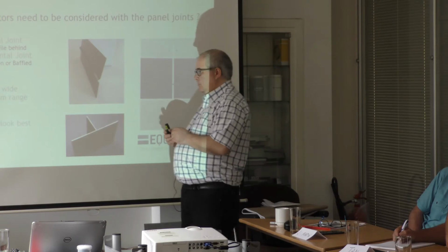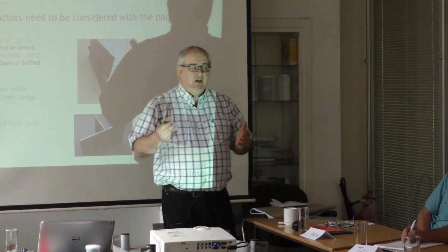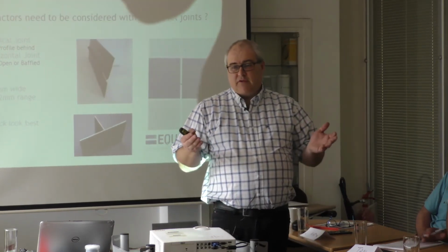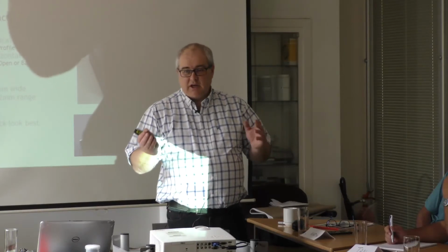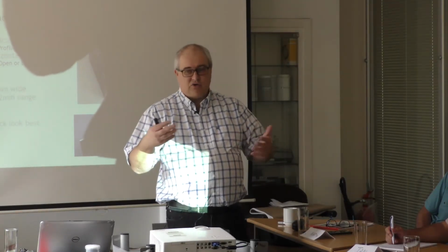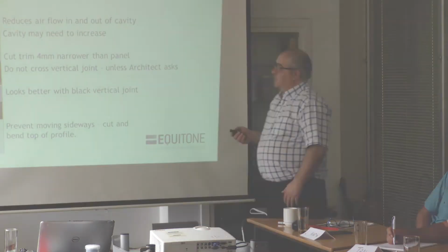Okay? It also makes setting out a lot easier. A lot of the time I've seen on architect's drawings to give you the size of the panel. And that panel might be 1586. It's a lot easier adding 10 millimeters for centers of joints to that figure than adding 8 or 12. Yeah? Okay. Nearly finished, then we can have a break.